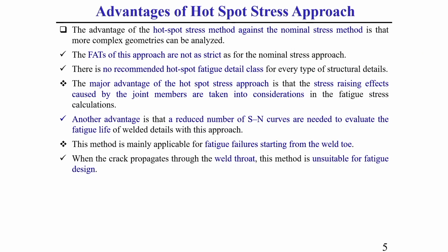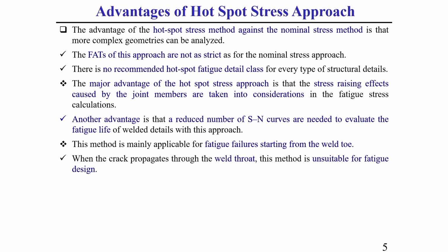What are the main advantages of the hotspot approach? The advantage of the hotspot approach compared to the nominal stress approach is that it is mainly used for more complex geometry, where the nominal stress approach is not feasible.